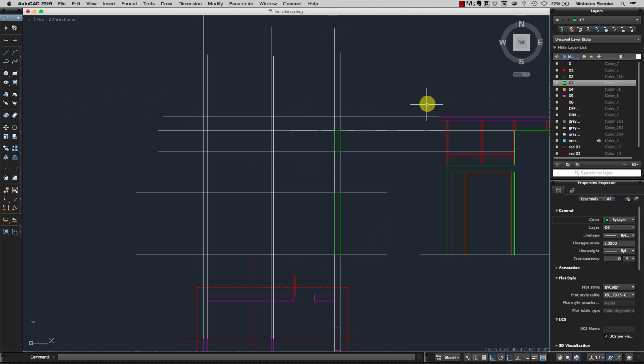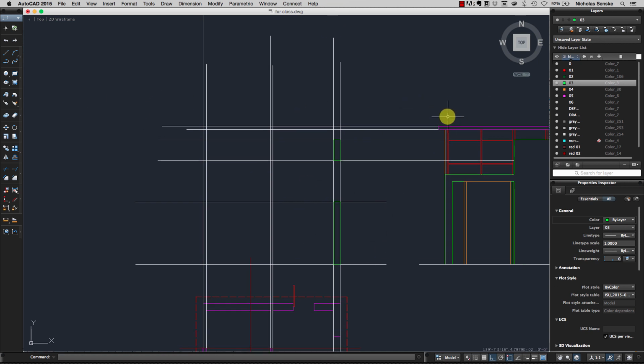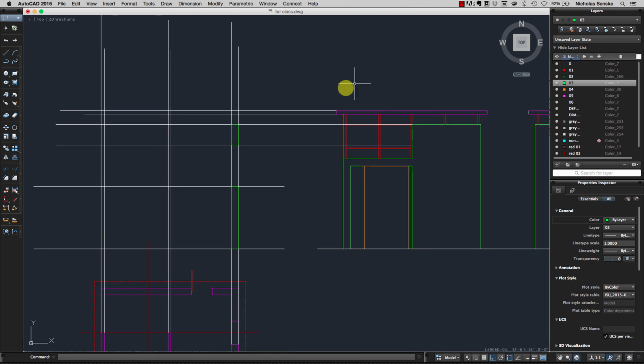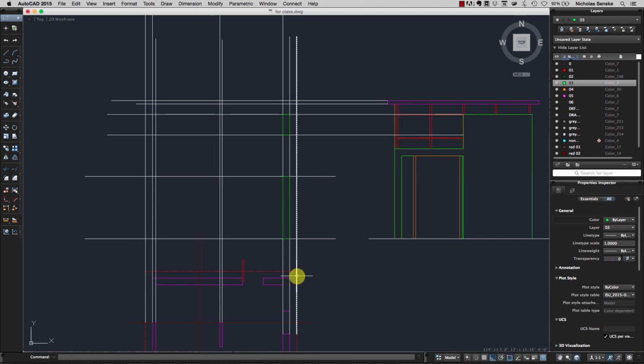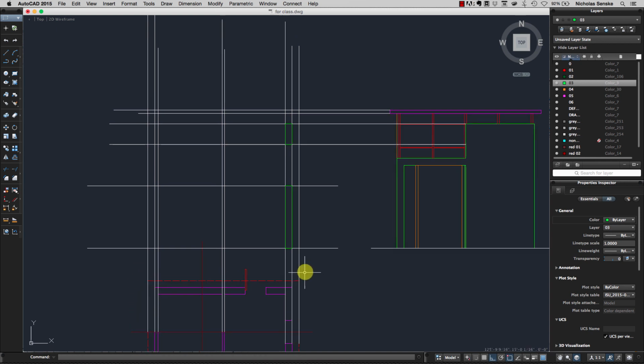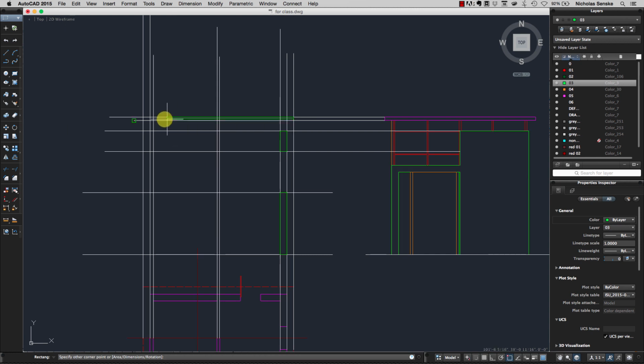Than to have the lines crossing everywhere. Remember, the parapet actually goes out a foot in both directions. I mean, we're cutting through this plan. I mean, sorry, this elevation. We're just going back further. So what kind of passes here should actually pass here? So you just do offset 1 foot. Offset 1 foot, and see it starts to line up. And actually, I guess I could have projected off of the overhang line that I created as well. That would also work. I'm just going to go ahead and finish this off here.